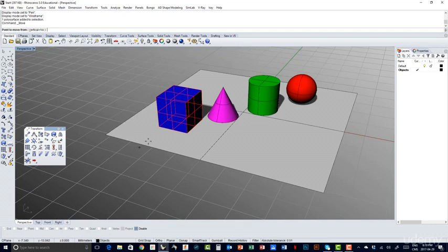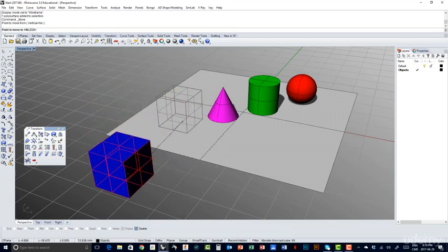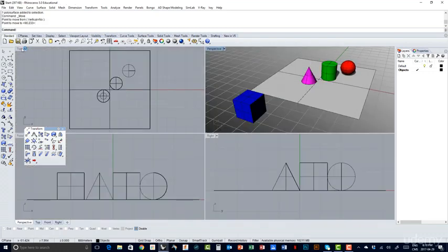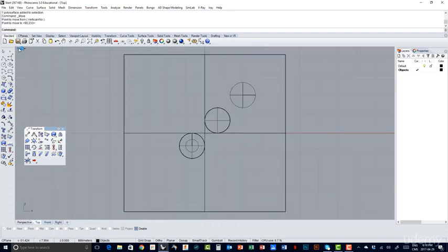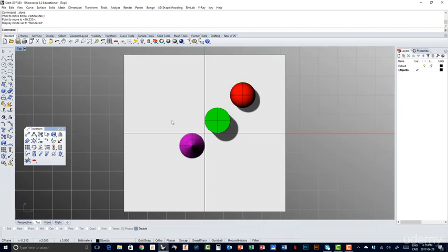So for example, I can choose this point randomly, and I can start choosing where I want to put it in terms of destination point. So I just left click again, and I've just moved it as such. Okay, so if I double click and maximize the top viewport, and I right click to go into a rendered mode, I can, for example, do another move.